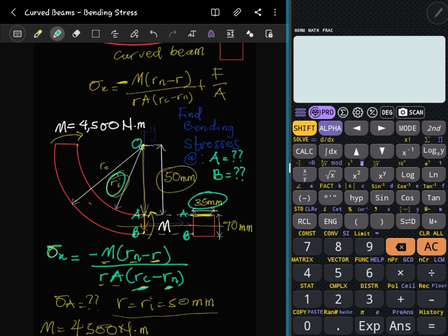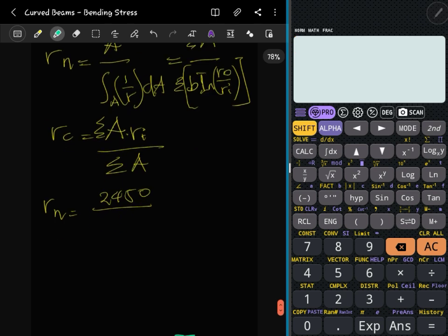So it moves and then comes to the outer fiber. When you take the cross section of the beam, the width of it, kind of like the thickness of the beam, that's the b that we're talking about. That's the 35.